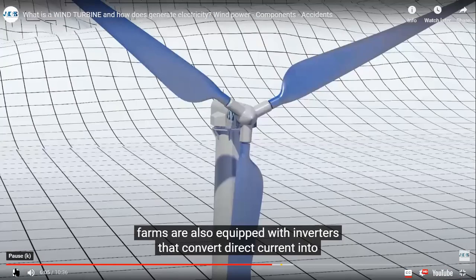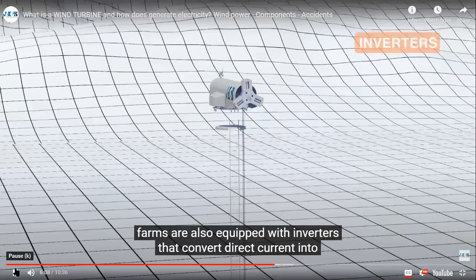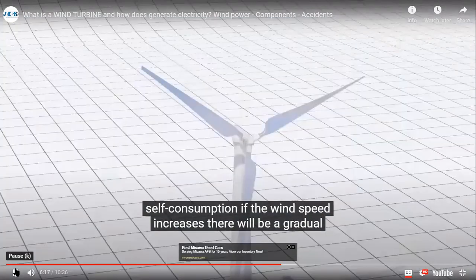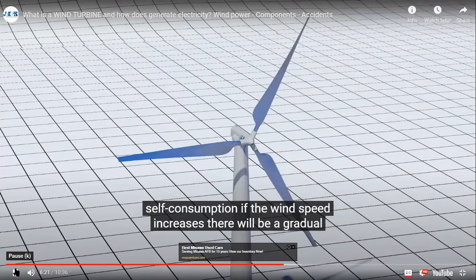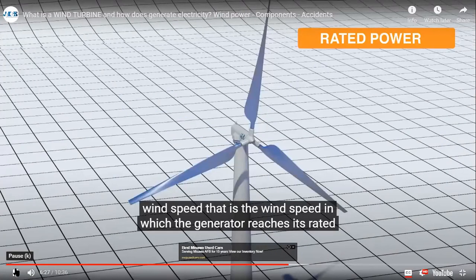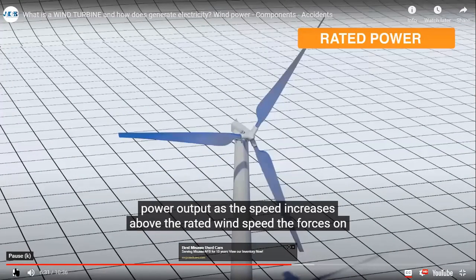Most wind farms are also equipped with inverters that convert direct current into alternating current at 220 volts, making it suitable for grid feeding or self-consumption. If the wind speed increases, there will be a gradual increase in the instantaneous power of the turbine until reaching the rated wind speed. That is, the wind speed in which the generator reaches its rated power output.